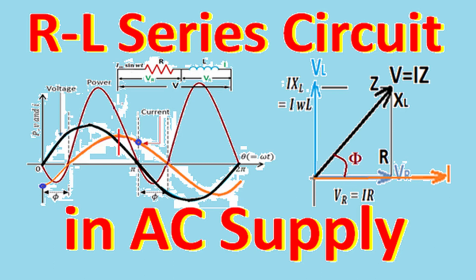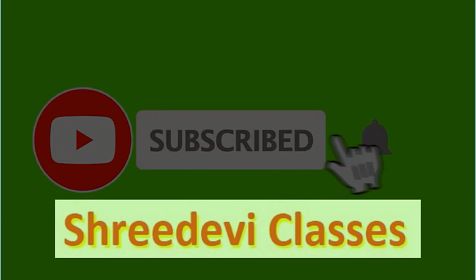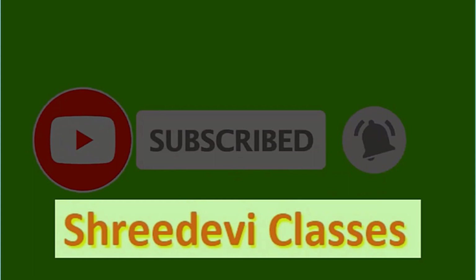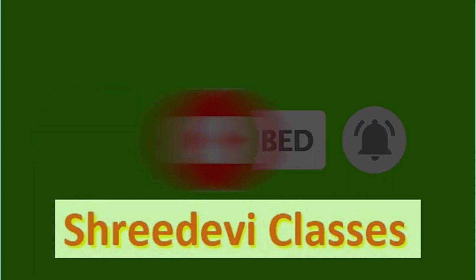Today in our playlist Basic Electrical Engineering and Class 12th Physics, in our chapter Alternating Current Circuit, we'll learn the behavior of a resistance-inductor series circuit in an alternating current supply, and will understand the concept of impedance, which opposes the flow of alternating current in an RL series circuit. In an RL series circuit, current lags voltage by a phase angle between 0 and 90 degrees, and the value of the phase difference angle depends upon the ratio of inductive reactance and resistance. So let's understand the RL series circuit, the concept of impedance, and the calculation of phase difference.